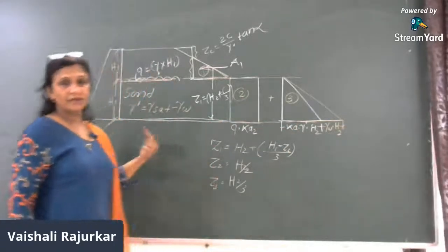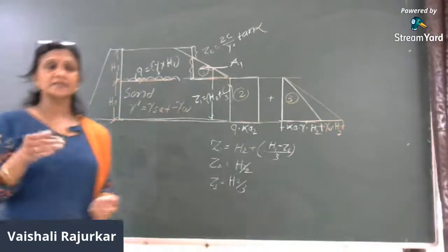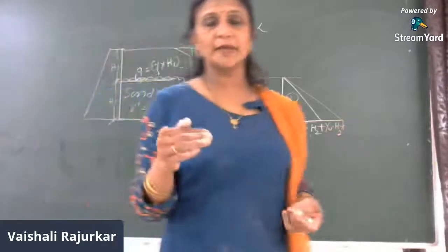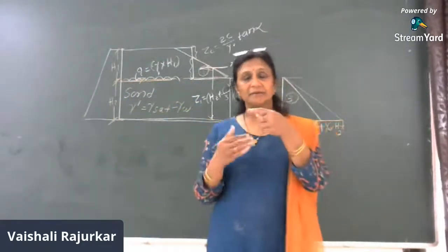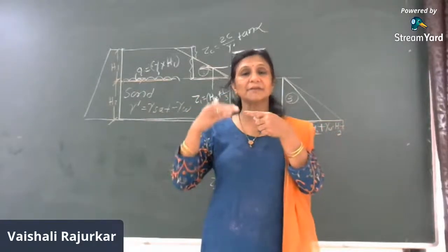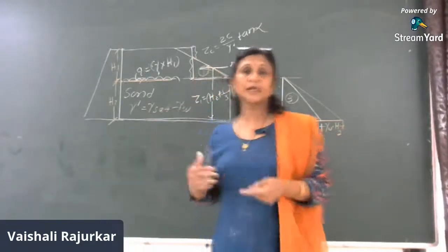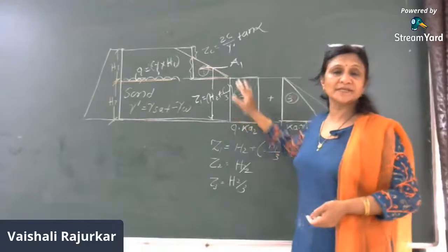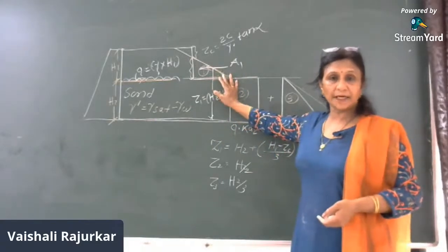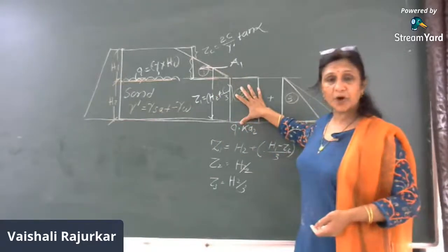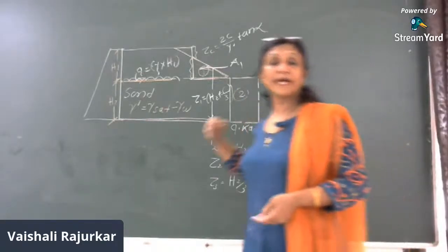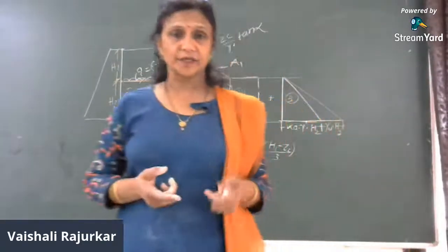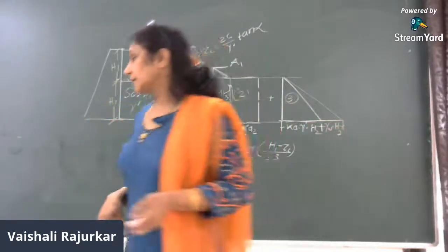So in this way, whatever extra things come into the problem, we have to consider in the numerical. Many times the numericals combine both sandy and clay soil, so you have to consider them independently, right? But when we are considering the bottom one, we take the combined area of both diagrams when there is a clay soil, right?